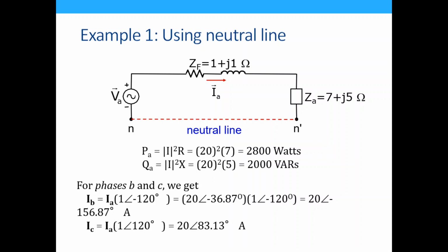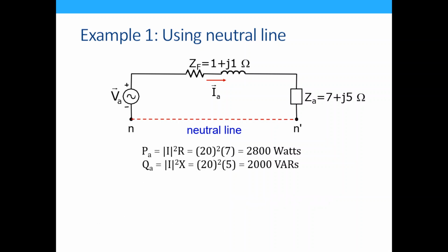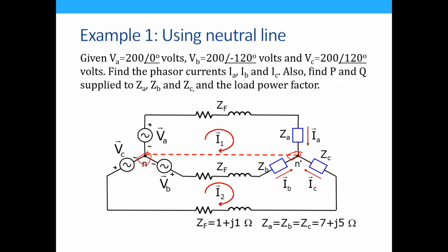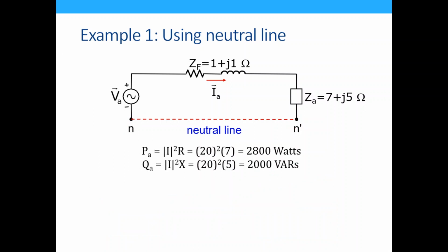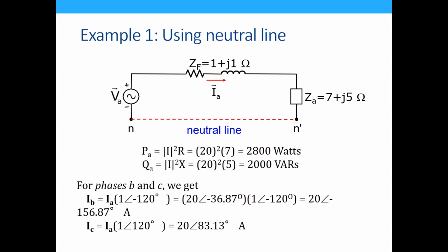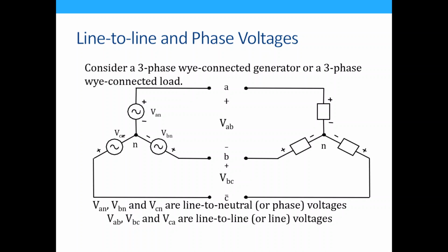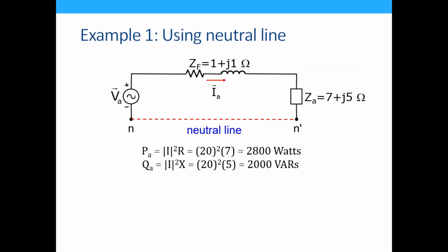All right. So that's how you solve a balanced three-phase system. Instead of doing this mesh analysis, you can actually decompose it into three single-phase circuits. And if you solve one single-phase circuit, you can solve all others just by knowing the relationship between the phases. Okay? So here you go.